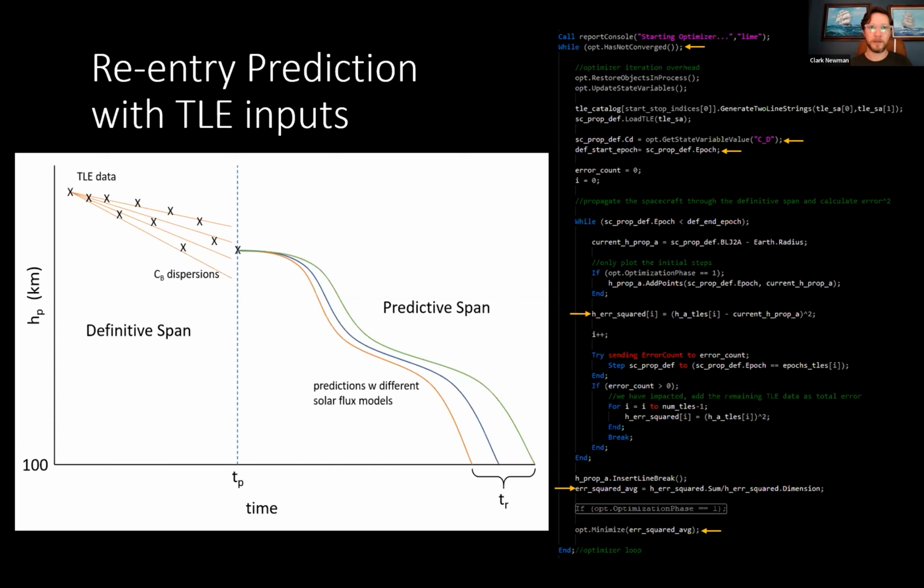The most simple, straightforward way to do this for any satellite for which you don't have explicit tracking data would be to grab the two-line elements that are published on it from a source like Space-Track or CelesTrak, which have an enormous database of two-line elements for every orbiting object in low Earth orbit that has a radar cross-section of 10 centimeters squared or above.